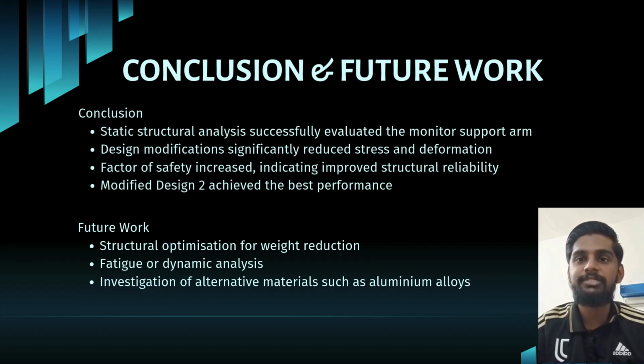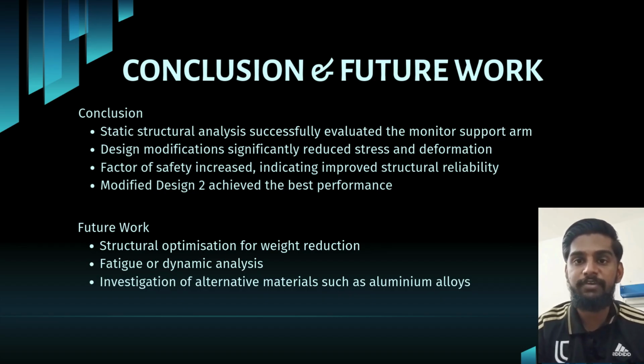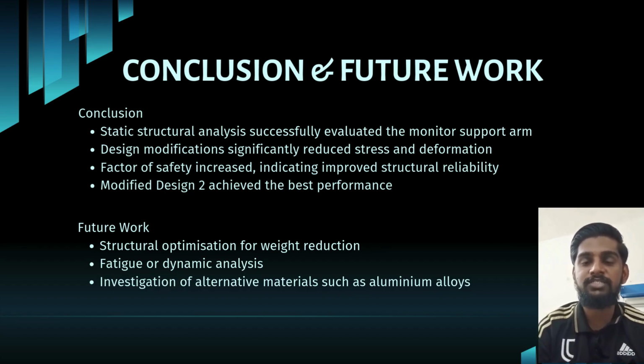In conclusion, a static structural analysis of the wall-mounted PC monitor support arm was successfully conducted using ANSYS. Three design configurations were analyzed under the same material properties, boundary conditions, and loading conditions. The results show the proposed design improvements effectively reduce stress and deformation while increasing the factor of safety. Among the three designs, design 2, which involved increasing the thickness of critical components, demonstrated the best overall structural performance. Therefore, the objective of this project was successfully achieved.